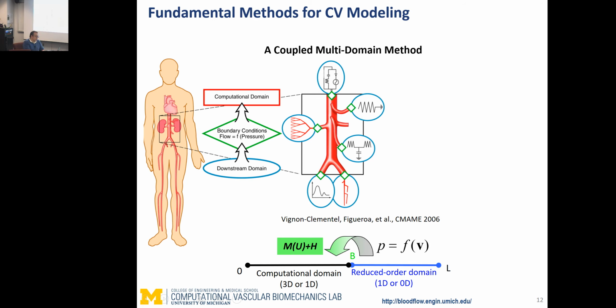The simplest model is a resistor. It relates a change in pressure with a flow, or in circuit theory a change in voltage with current. You can make more complex models, maybe adding some capacitors, some diodes, etc. Or you can have linear propagation theory or an impedance function. The idea is that it's a simpler model, but nonetheless it's something that you can couple at this interface between the three-dimensional domain and the boundaries.